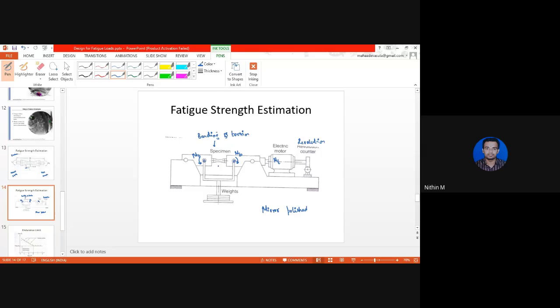So here we will polish this specimen in such a way that it appears as a mirror. It is almost similar to these Belgium mirrors, those costly mirrors that you see. Thereby preparation of this specimen is a very costly task. There should not even be a minute scratch even when you observe it under a microscope with a magnification factor of somewhere around 30x. That is the level of finish that is required. So it is a carefully polished specimen.